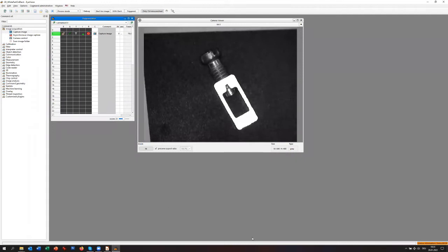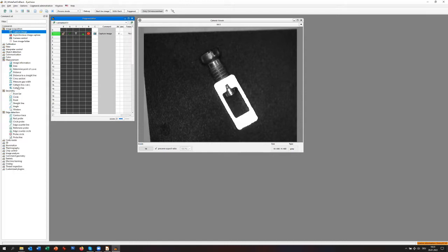Today we will focus on measurement. That means, of course, we need the image capture tool, and because we want to measure, we need to find edges. Edges are the basis of measurement. After you have some edges, you could use the basic geometry to do some measurements, or you also can use some complex tool like the free caliper to do the measurements. Of course, for everything, it was true yesterday, and it's more important today.